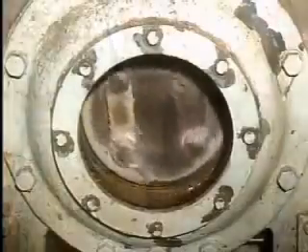The fact that oil is available in many different viscosities makes it a good lubricant in a wide range of applications. In addition to providing lubrication, oil is also used for cooling machine parts. Fast-moving gears such as these can build up quite a bit of heat from friction caused by the teeth rubbing together. The oil picked up by the gears not only lubricates them, but also carries the heat away.